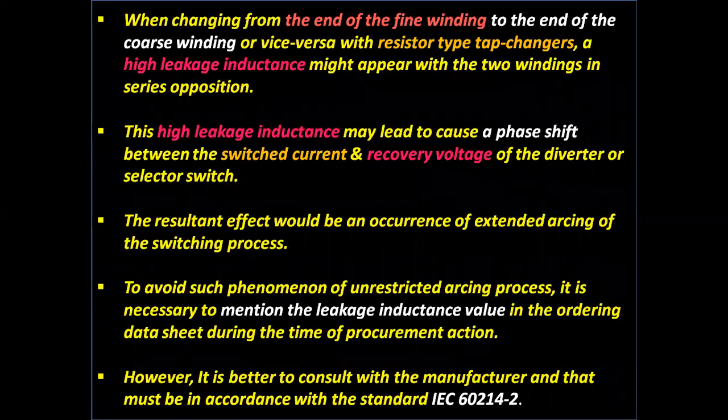When changing from the end of the fine winding to the end of the coarse winding, again I repeat, when changing from the end of the fine winding to the end of the coarse winding or vice versa, with resistor type tap changers, a high leakage inductance might appear with the two windings in series opposition.